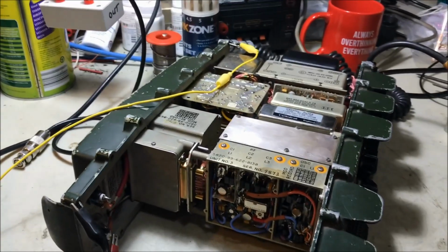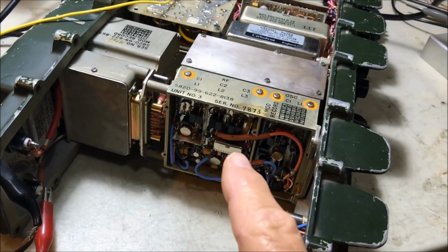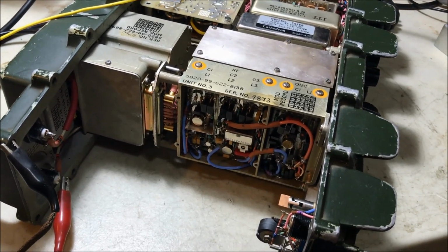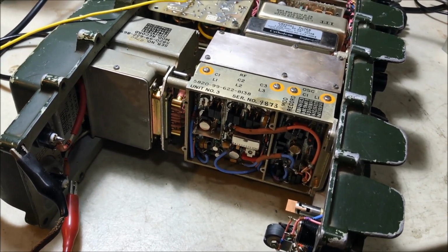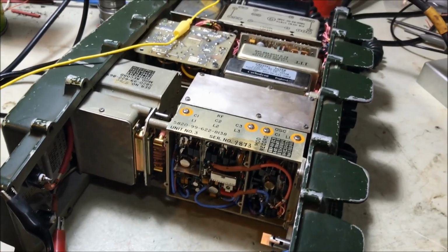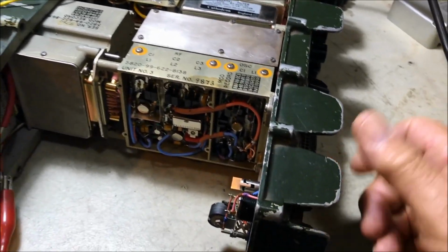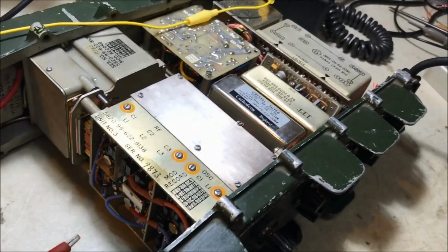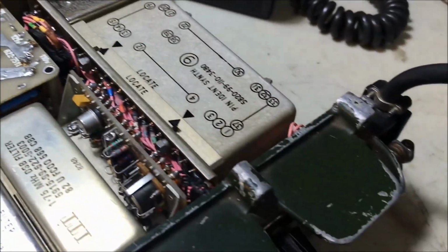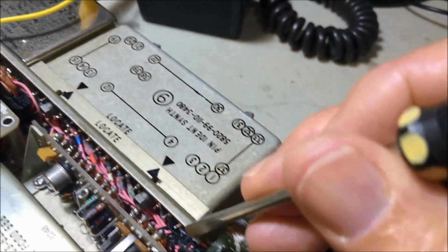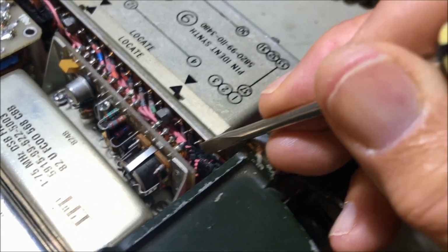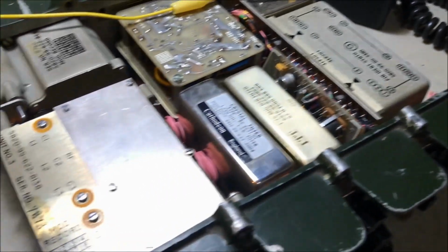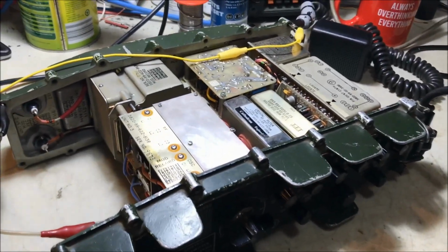So what we're going to do is disconnect this particular wire here from behind the synthesizer, and we're going to inject 15.28 volts in, and we're going to see what happens to the wobble. So let's get in behind that synthesizer. And by the way, I was saying before that it's very close in behind the synthesizer, and if you look at it here, the wire that we're talking about is right down inside there. And look, at this point, I'll tell you the story about these radios and the wobble.